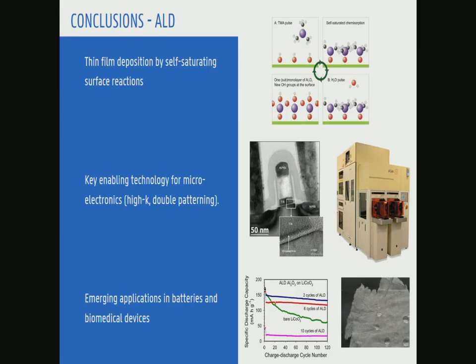So that brings me to the conclusion. I hope that I have convinced you, or that I have been able to demonstrate, that this is the principle of ALD. You're depositing a thin, usually inorganic film by self-saturating cyclical exposure to two gases and self-saturating reactions during those exposures.